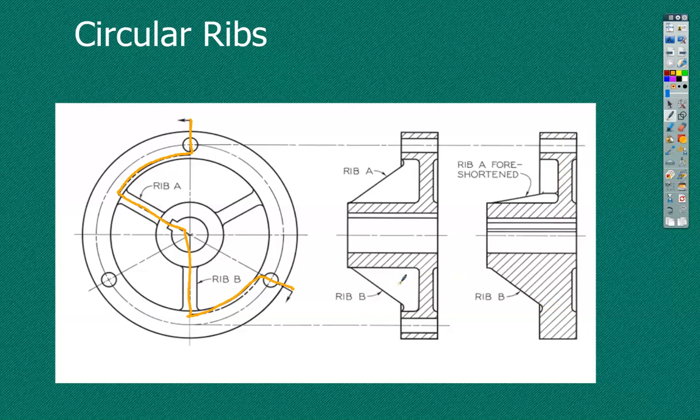So if I just did a half section just so that bottom half, but I still need to fix the hatch on the rib, that would be fine. But I'd want to go through the hole. But still need to at least do that piece of it. If the hole was here, if you take just pure half section, no problem. But because the hole is not aligned with the rib, now we have to do some work.